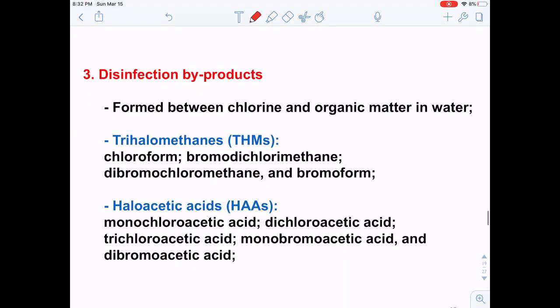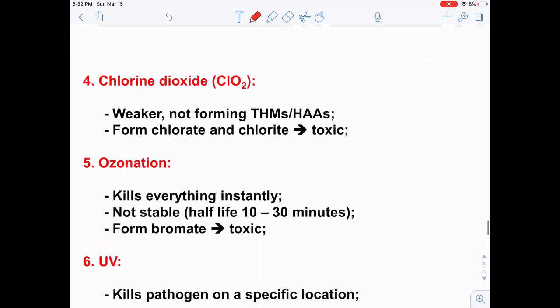species in the water. Okay, so one thing we need to pay attention to in chlorine disinfection is the disinfection byproducts. During the disinfection, the chlorine can react with many other species, and mainly it is the existence of the bromide in the water that's going to cause the formation of these byproducts, and most of the time they're toxic. These byproducts might include the THMs or HAAs. Here I won't further introduce what these species are, but we need to closely monitor the concentrations of these byproducts.